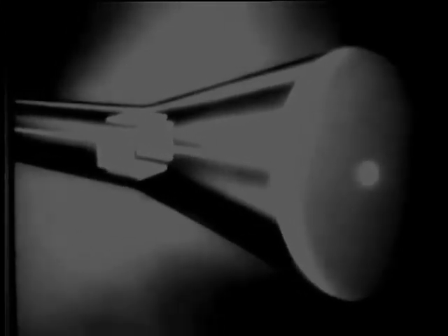Now that we know why such a scope picture is desirable, let's go back to the electrostatic tube and see how we can get a circular baseline using the horizontal and vertical deflecting plates. Here's a front view of the plates. The electron beam is dead center since neither of the deflecting plates has voltage applied to it. Let's apply some and see what happens.